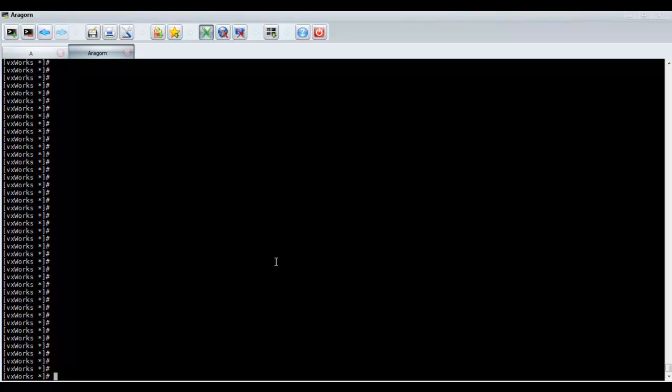I have a terminal connection to the board, and I am now able to run the OE admin executable. This is a tool that runs on the target itself and is a very small textual based tool. You need to give the OE admin tool a reference to the name service so it can look up the domain manager. So if I type that core block in correctly, what you can see is the main menu for OE admin.